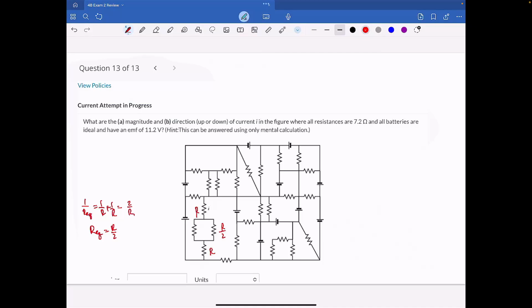They're all the same because they're all in series. So I can just add them up. That's 2.5, isn't it? So 2.5 R is the total, and if I can find the current through that 2.5 R equivalent, then I know the current in that single resistor.